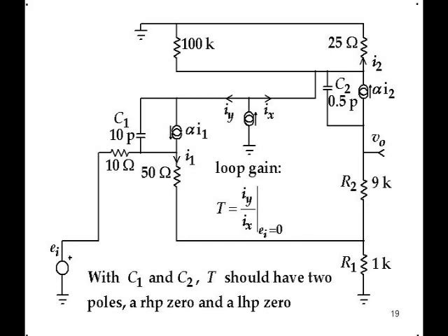Well, I didn't do that here, but this is a non-ideal injection point because looking back from the IY, it's not coming from an ideal current generator anymore because of the C1 capacitor. And that's why you don't get the answer that you expect from the loop gain. It's not that the calculation was wrong or incorrect, of course. It's that it's not giving you the answer that you wanted to get. So that's a sort of glaring example of what needs fixing.